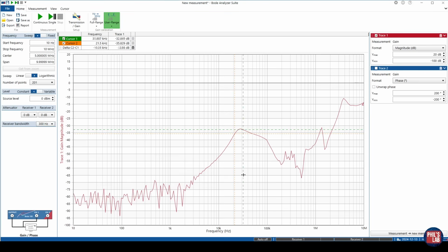And as we go high in frequency, we also have some peaks and dips and notches at various places, but overall the trend of the power supply rejection ratio is upwards, and that is worse and worse. At about 4 MHz, we're already at minus 10 dB of power supply rejection ratio, and this is a typical trend for regulators, in that we have pretty good performance close to DC, and we get worse and worse as we increase in frequency. And this has a couple of reasons.